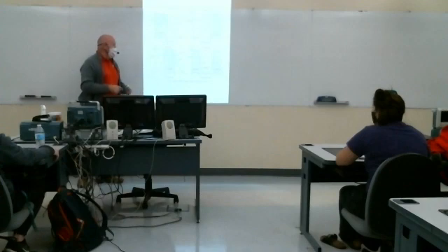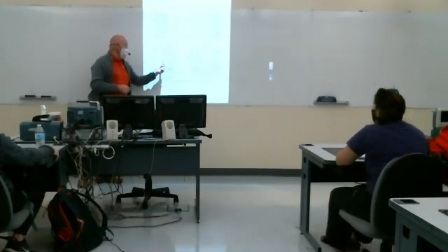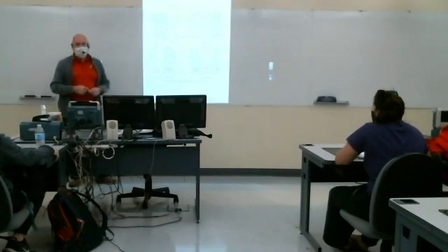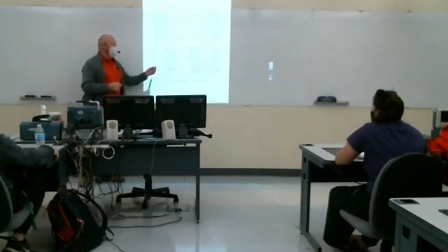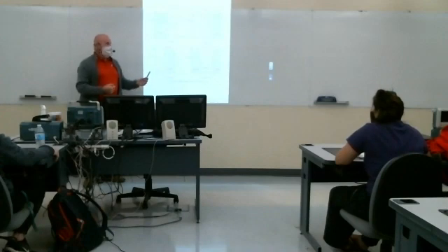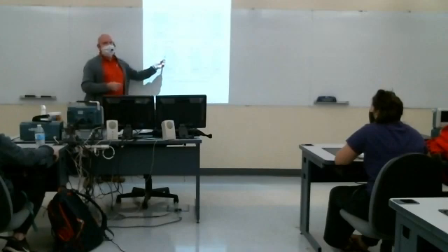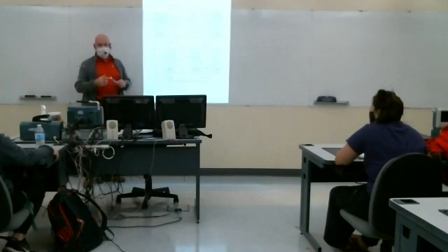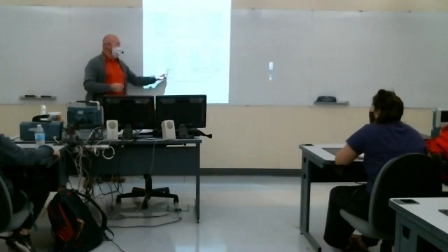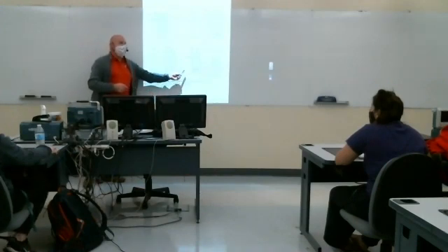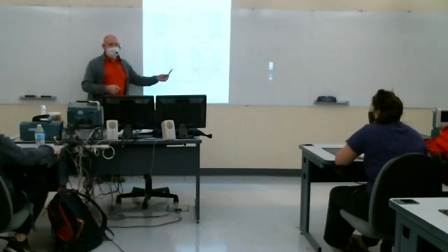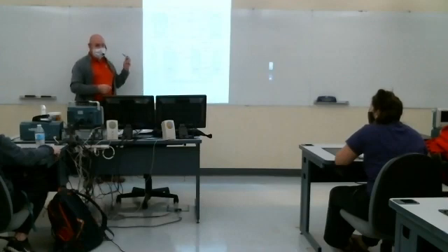Band pass filters, this is a band pass filter. It's designed to pass through a certain range of frequencies. The classic application here is for radio and television. If you want to listen to a particular channel or station, you would pass through that corresponding frequency. So, like on your FM radio, you want to listen to 98.6 megahertz. You want to pass through 98.6 megahertz while eliminating 98.8 megahertz and everything higher and 98.4 megahertz and everything lower.